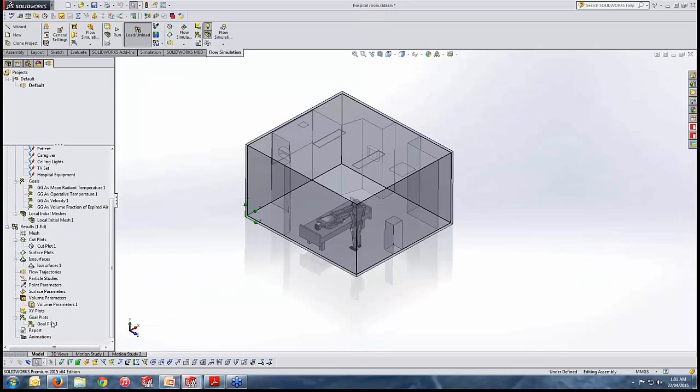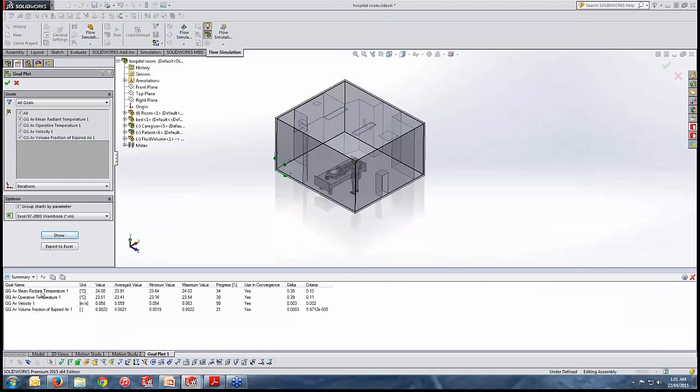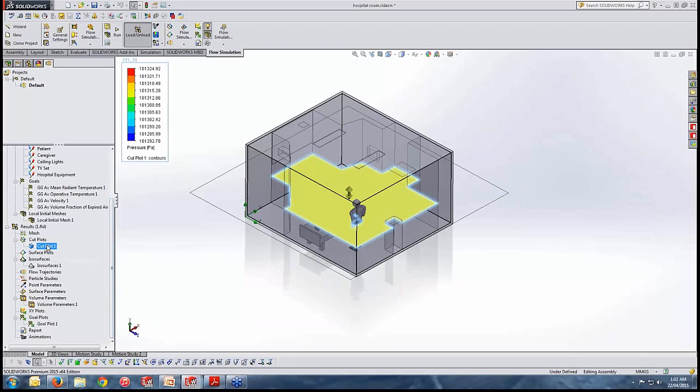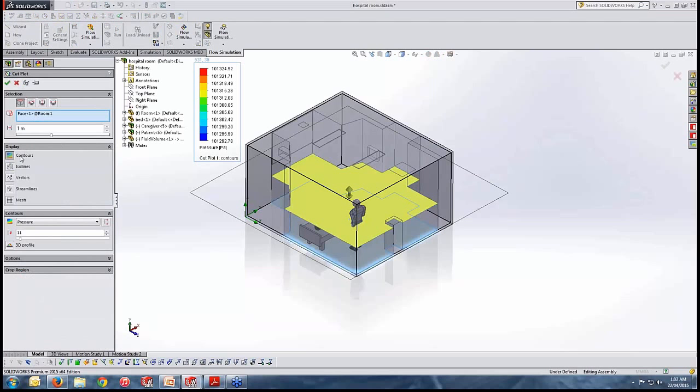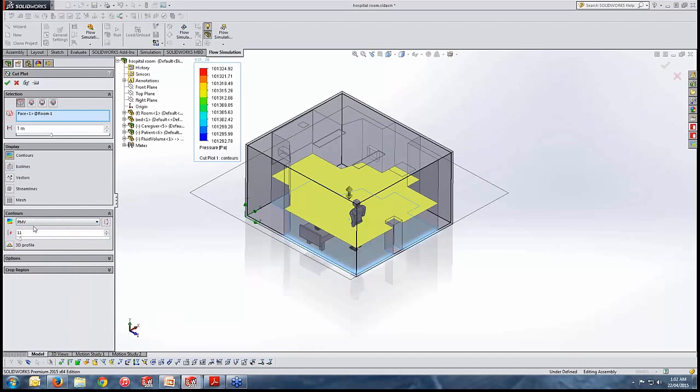The other thing we would like to have a look at is again our goal plots, looking at their value and telling us how accurately we converge our answer. These are the acceptable delta, and we are having a very fine criteria to converge. So I can rely on my answer here. Again, any goal plot, any cut plot can be simply activated by going to your edit definition, contour of pressure, or any values of human factors such as PMV, and show it and look at it here.